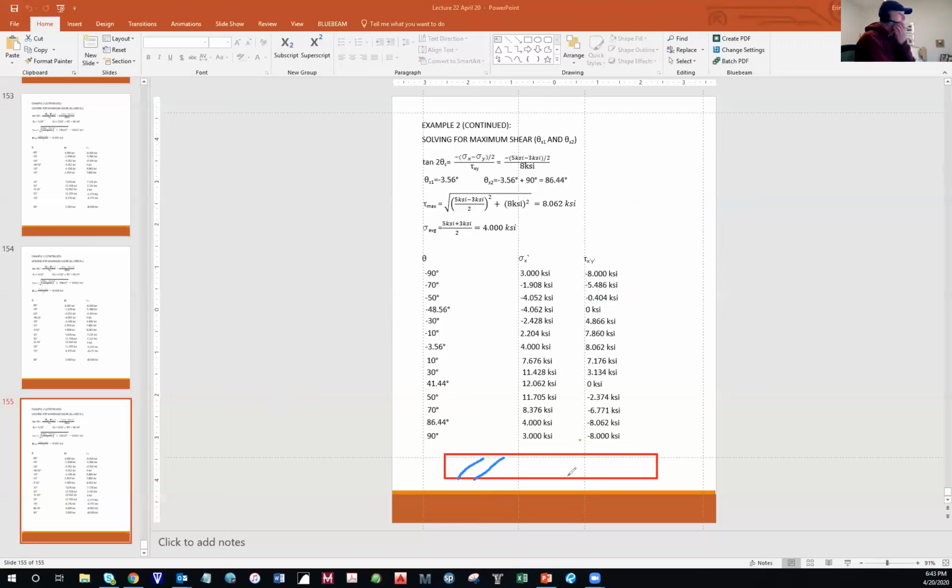Maybe this will help. Your equation for normal stress is My over I. So if I pull the cube out of here, then that cube is going to have a lot of compression on it from the My over I equation. But if I pull a cube out of here at the bottom, My over I is going to create a lot of tension in that cube down there. And this cube is near the center of the beam, so it has a little itty bitty shear on it.